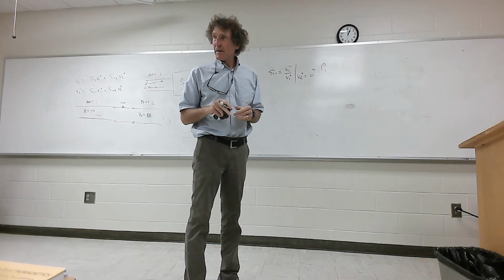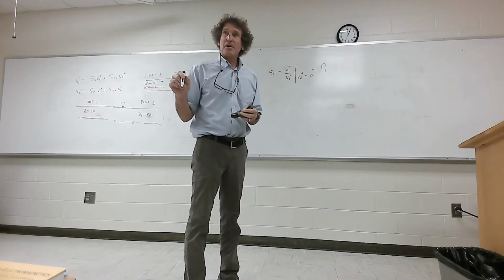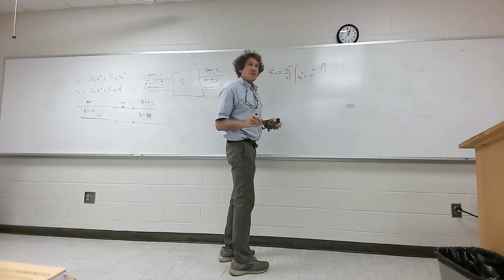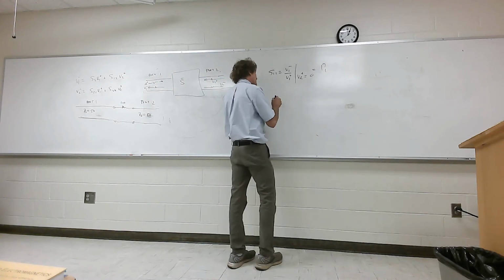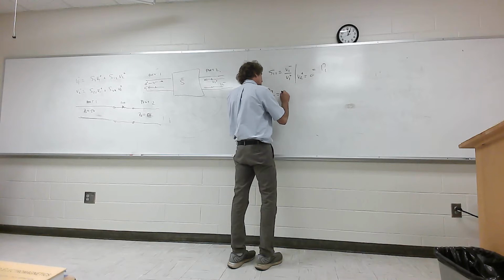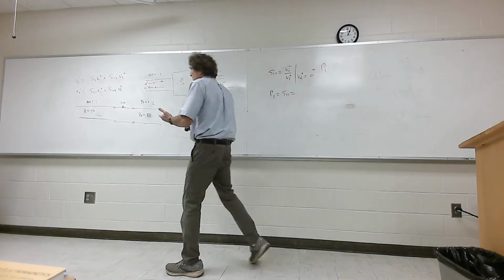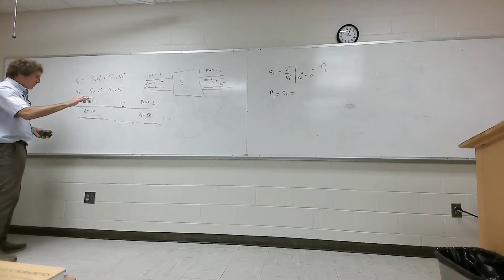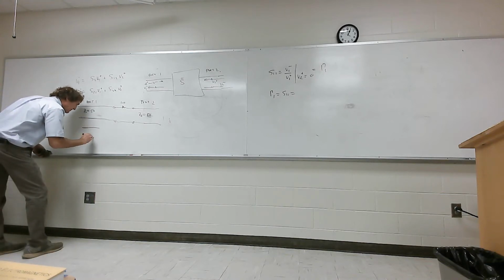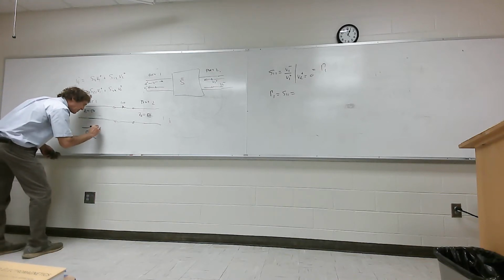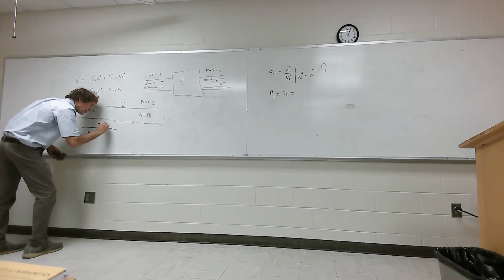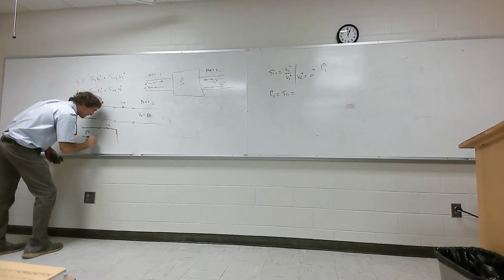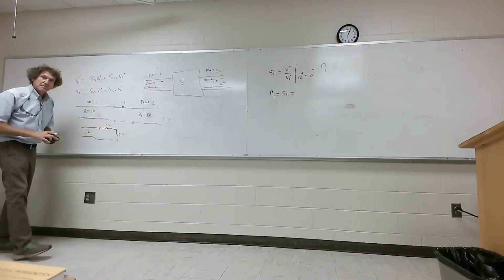Anyway, how do you get that? How do you get the reflection coefficient, which is S11? Well, it's always the impedance you're going into, correct? And if you look at port 1, over that way, this looks like you have 50 ohms, right? Then you have 100 ohms here, and you can model that 50 ohms as just a resistor, as if it was 50 ohms. You all follow me?